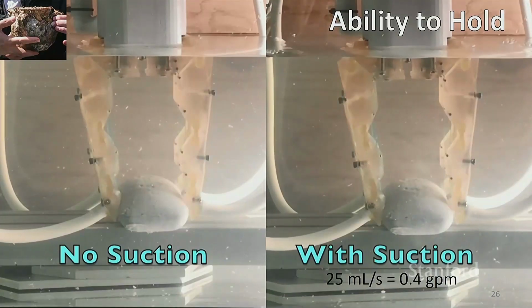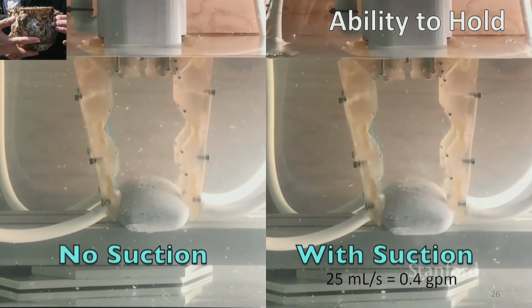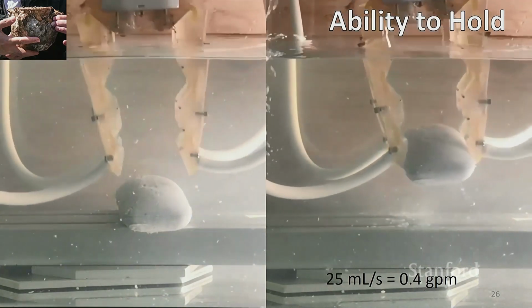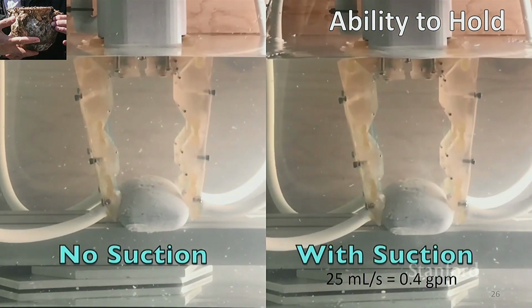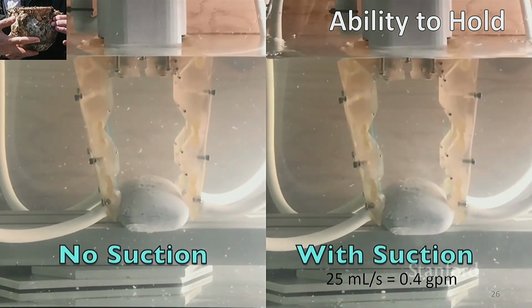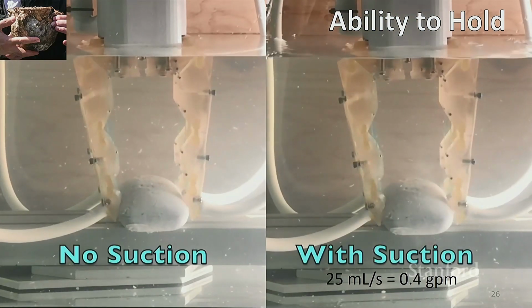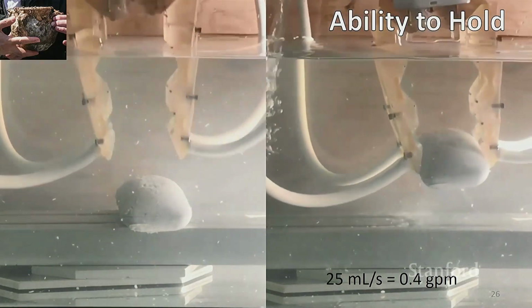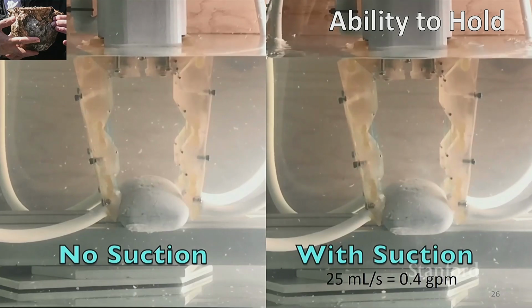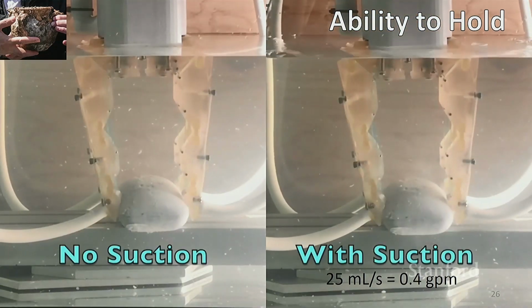One analogy would be a bar of soap that's maybe been sitting in water for a while. It's really kind of goopy and slippery. And you can see that without suction, with this particular hand, we're not able to pick it up. I guess we could put spikes on it, but now you're like spiking your soap. So instead, what you can do is add a little bit of suction flow to the fingertips, which means that the object is going to be attracted to that location, and you're able to pick it up.